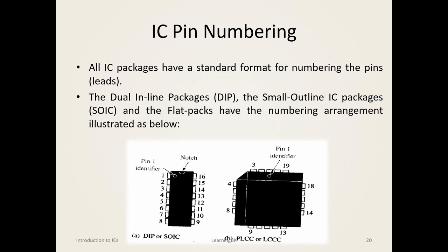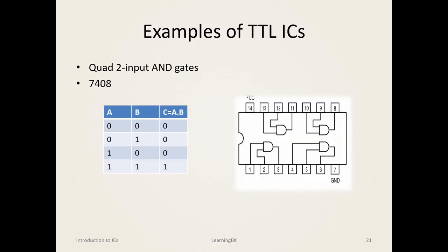As you can see, pin 1 starts to the left of this notch and continues in a counterclockwise direction. Now let's see some examples of the TTL ICs. These are the ICs that we would be using in our course as well. So for example, if we look at the two input AND gate in the TTL family, the number for this IC